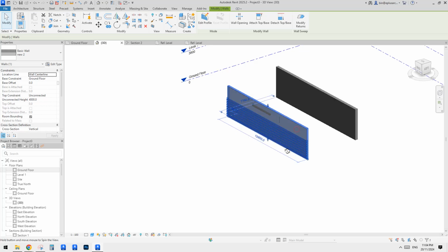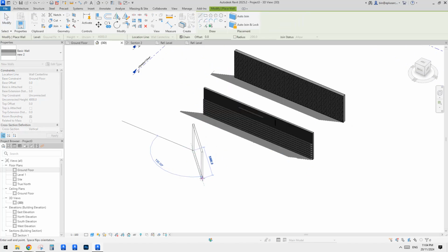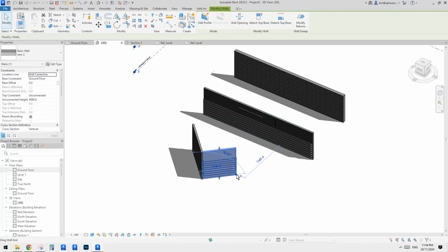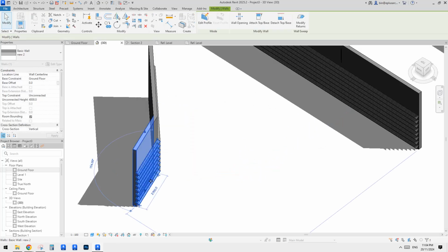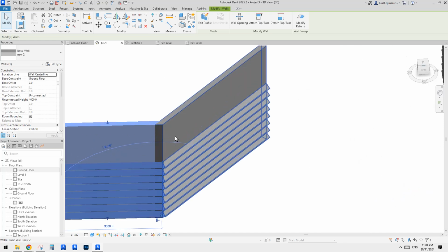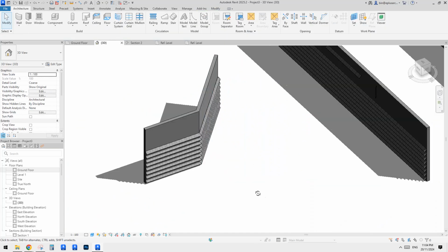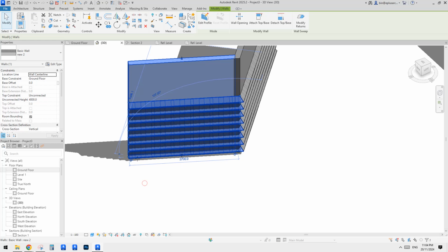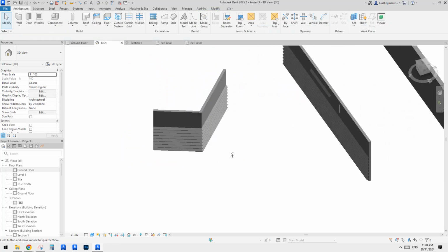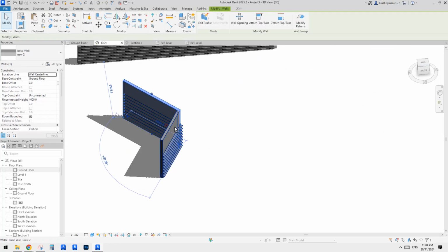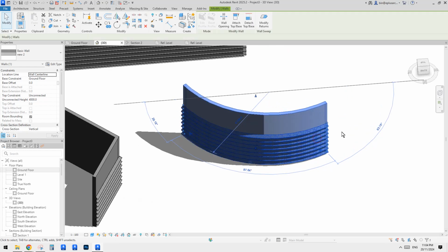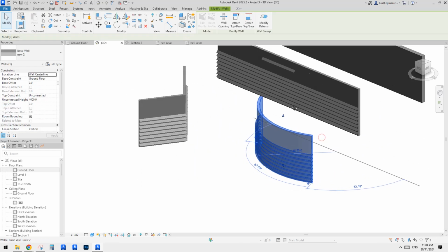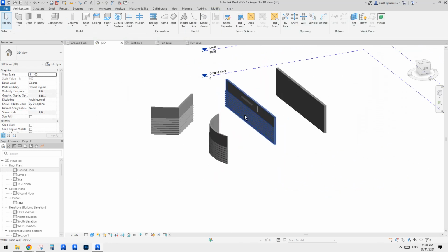And also for this wall, you can create a single wall, you can create multiple, you can trim them so they automatically match, trim, fillet, whatever. And also you can do an arc curved wall as well, and it works. Maybe press space to flip it, right? So okay, that's that.